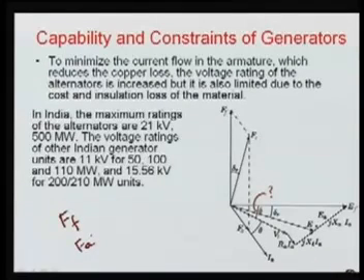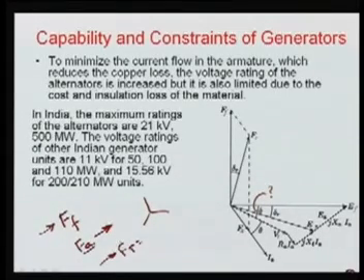If you see here, we have the armature currents, and because we have three phase windings displaced by 120 degrees in space, the resultant Ft will also be rotating in the air gap. This flux, that is MMF, will be rotating at the speed of the operating frequency, omega equals 2 pi f. So Ff is rotating at the synchronous speed, and Ft, due to Fa, is also rotating with the same speed.